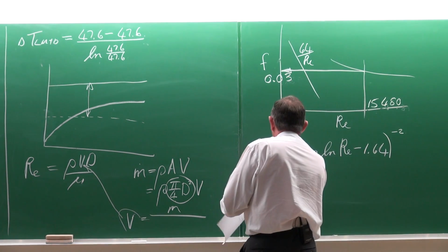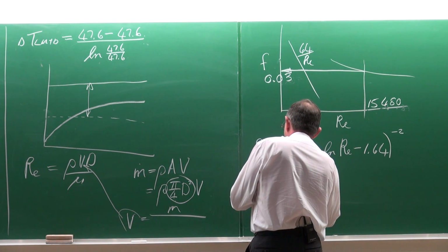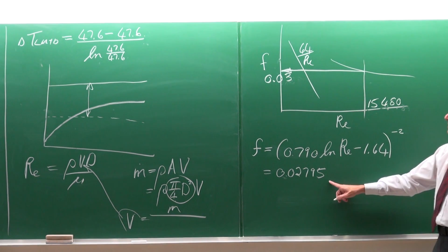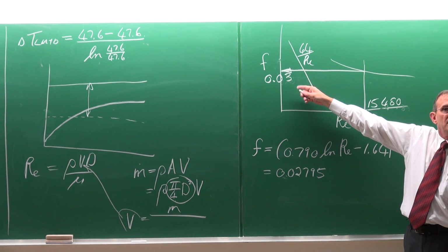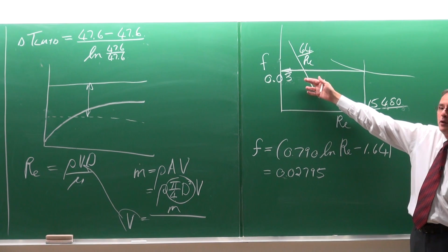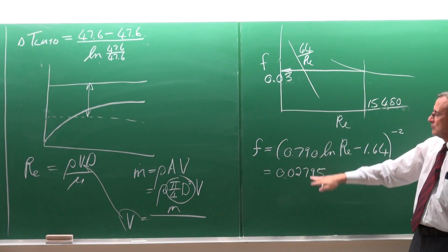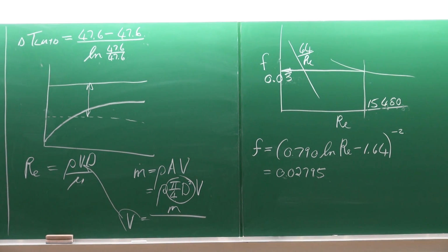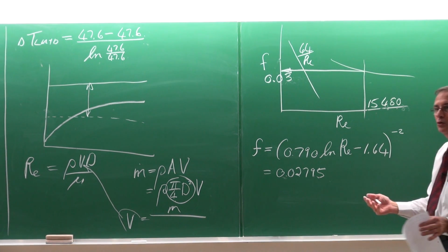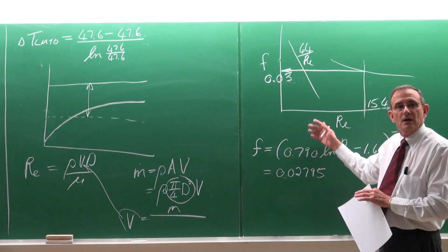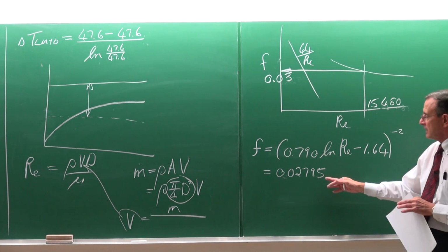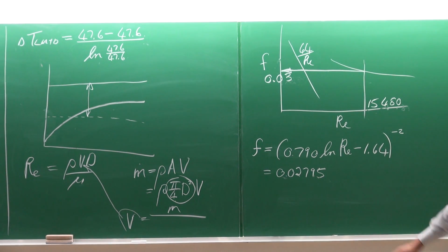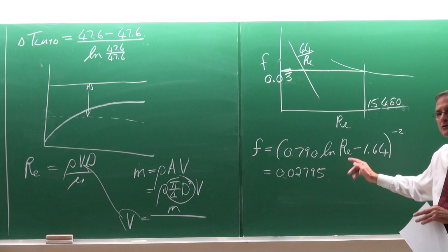If you calculate it with that, it is actually equal to 0.2795. It's not very easy to get values from the Moody chart that are accurate to more than about one significant figure. However, what I always do, when I do the calculation, is quickly look at the graph to see if it's about right, because it's very easy to make a mistake. So it's very easy to check.